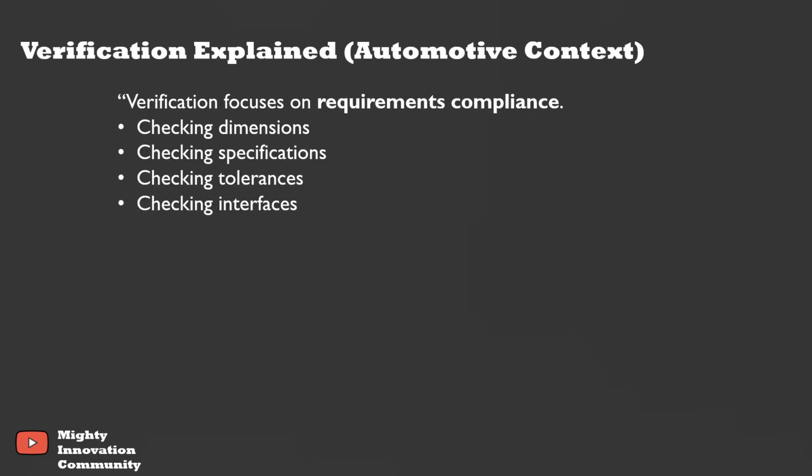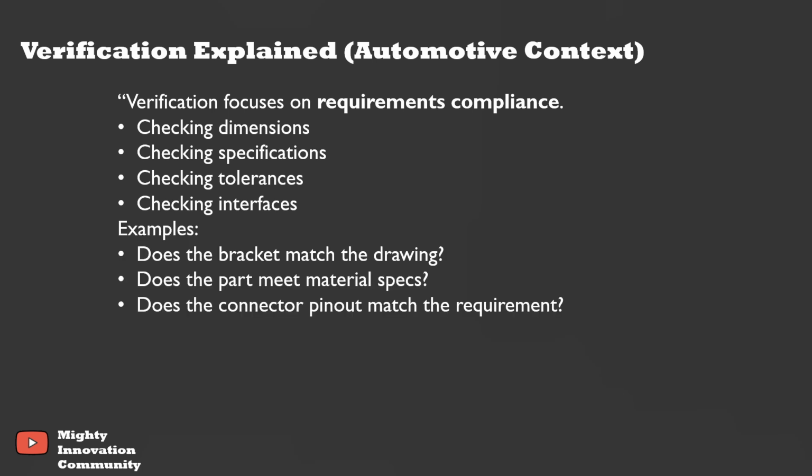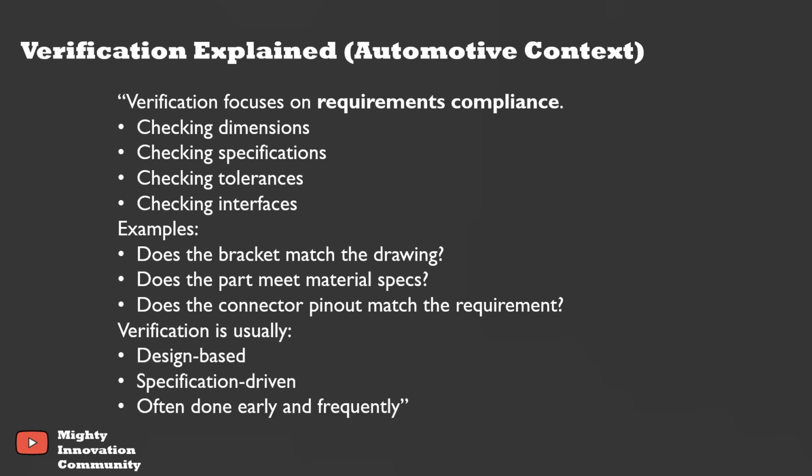Verification focuses on requirement compliance. In automotive, verification means checking dimensions, checking specifications, checking tolerances, and checking interfaces. For example, does a bracket match the drawing? Does the part meet the material specs? Does the connector pinout match the requirement? Verification is usually design based, specification driven, often done early and frequently in the program.